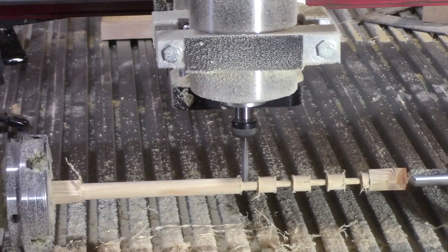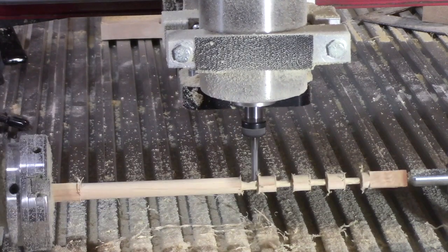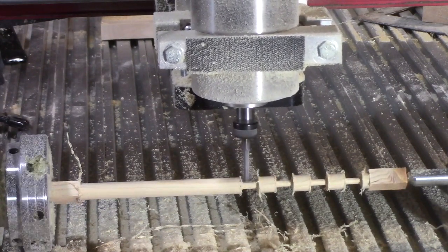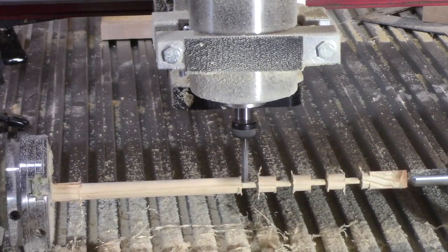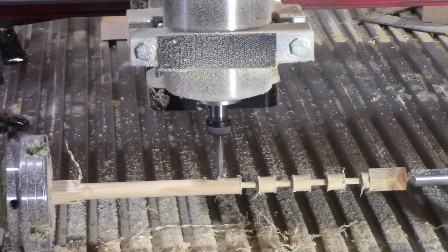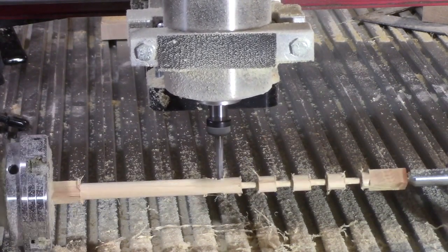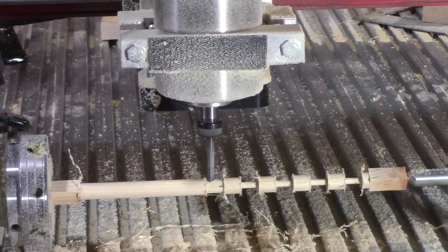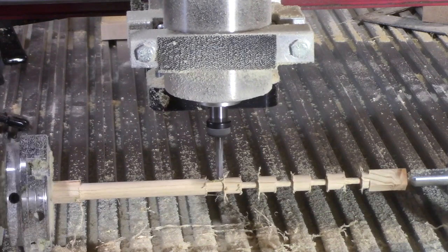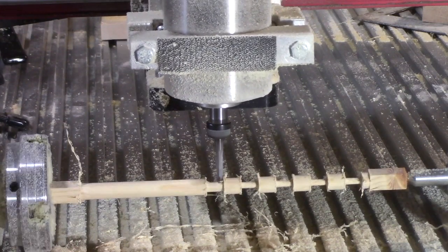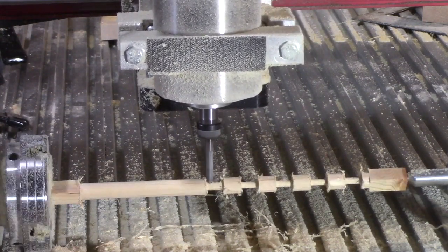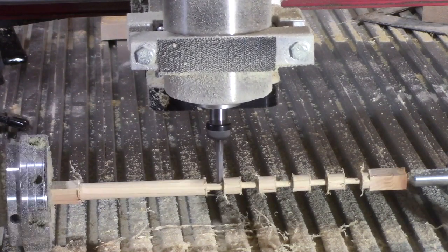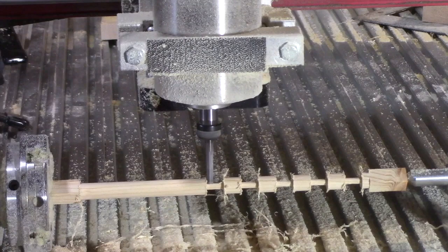So the other trick I've learned is the block on the far right where it touches that. I put one little drop of oil in that before I attach it to the machine. And it's far enough in that it doesn't seep into where the parts that I use. And that keeps it lubricated and keeps the friction down a little bit as it's spinning. You don't have to do that, but I chose to do it because I'm making such a small rod that the vibration can be a little bit aggravating.